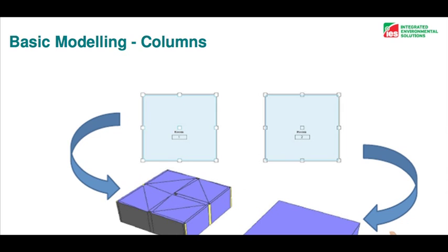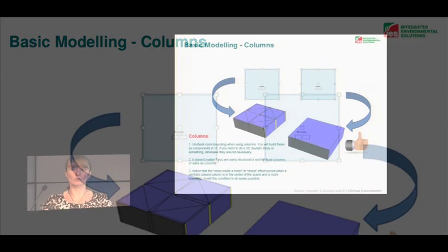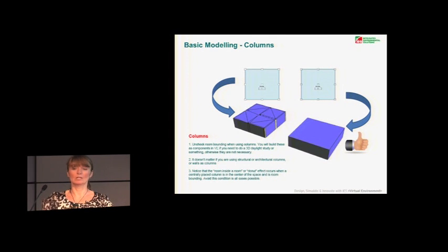And that creates a situation in the virtual environment which it doesn't really deal with very well, where it sees a room within a room, okay? Just by setting those columns to be non-room bounding, we get quite a clean room there that we can import very easily.